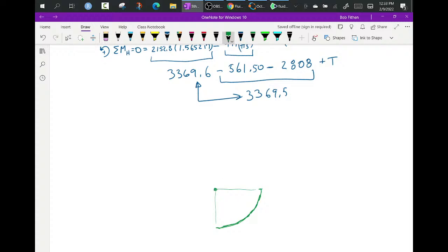Well, if this is full of water, say this is air and this is water, something interesting happens. And we talked about this earlier. If you have an area and you have a high pressure here, your force direction is dictated by the orientation of that area. In other words, if I did this and the pressure high was here, then essentially the force direction would be oriented normal to the area.